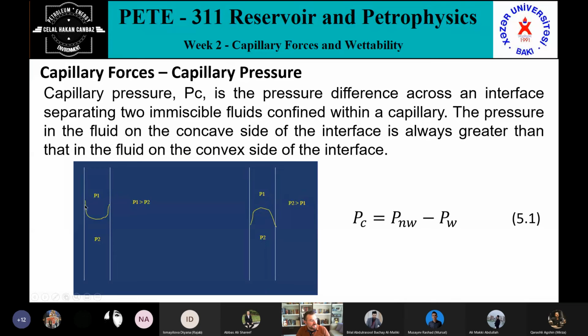As you can see, P2 has a tendency to catch the surface. It continues to catch the surface and doesn't leave it. Because of that, you can understand that P2 here is the wetting phase, judging by the surface interaction. So in this one, P2 is the non-wetting phase and P1 is the wetting phase because of the same behavior.